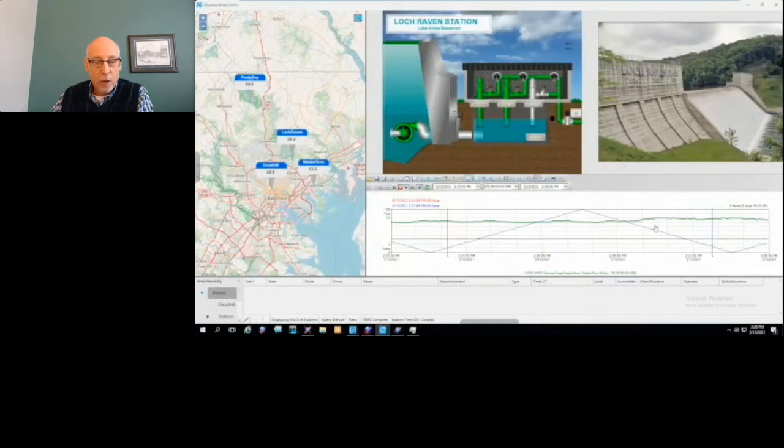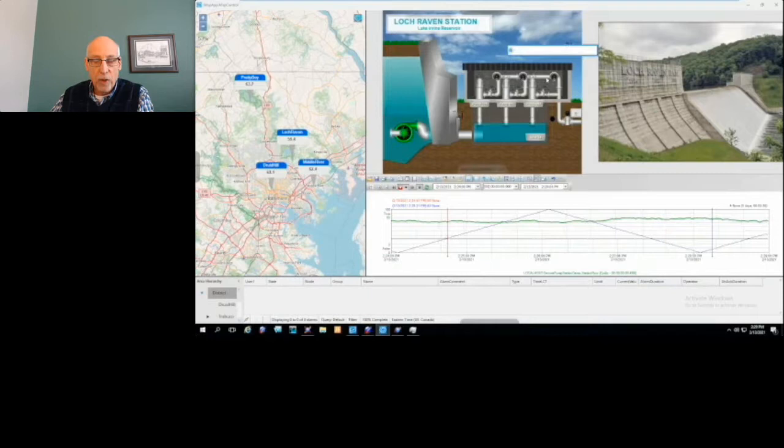So let's talk about a relatively new feature we have within our graphics, the ability to enunciate alarms on the actual graphics to get the operator's attention. And we saw previously we can enunciate the alarms on the trend controls and things like that. But if we want to get the operator's attention, we have some built-in functions that allow us to do that. So we're going to go here and generate an alarm on our process. And we're going to see this alarm border animation show up.